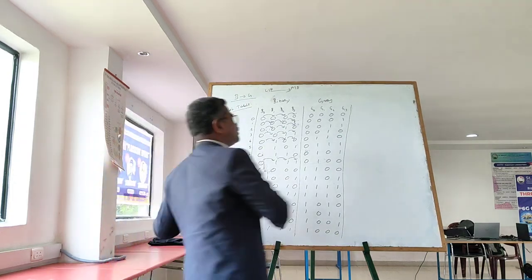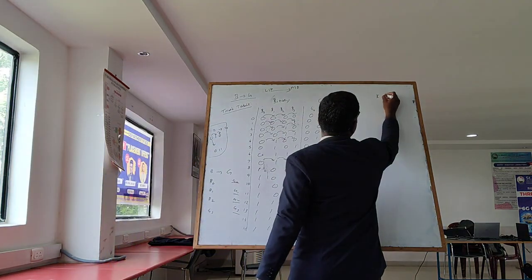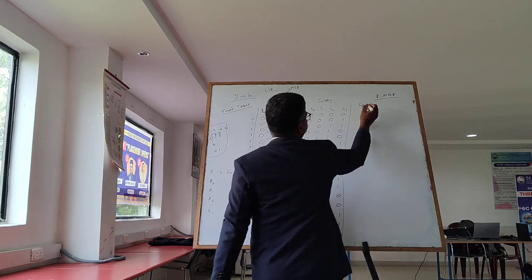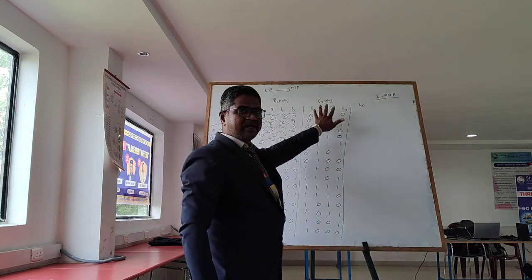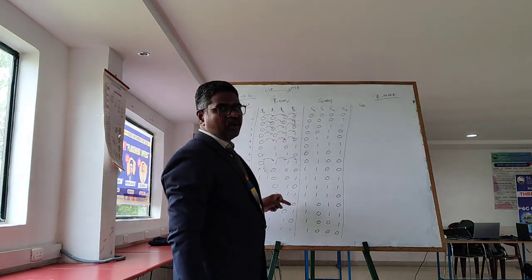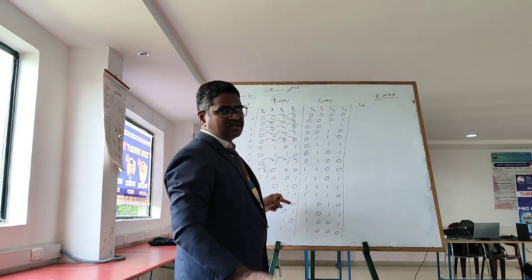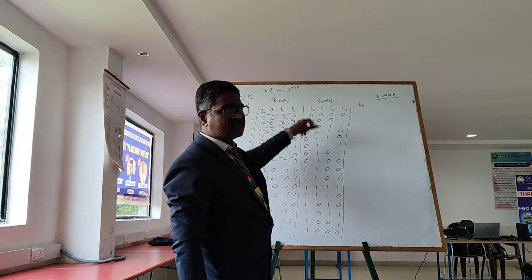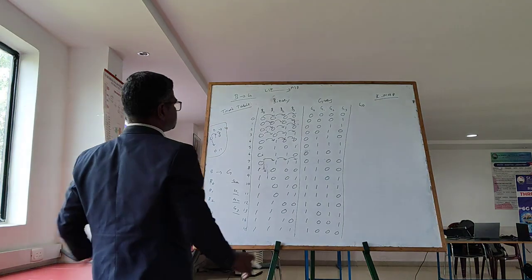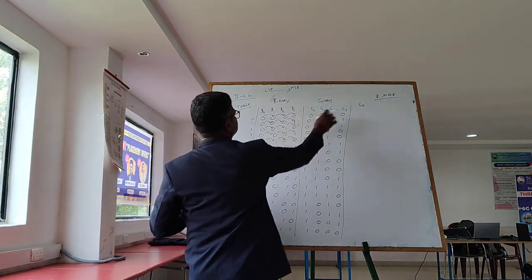So let me make the first K-map for G0. So now only I am concentrating on gray code. Wherever 1 is present, we have to make 1 in the particular boxes. Rest nothing, right? Similarly for G1, G2, G3, right? So let me erase this. Let me cross check. 0, 0, 0.